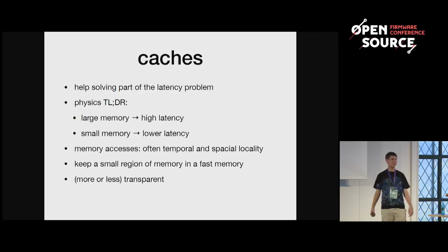What's used on some ARM microcontrollers is the tightly coupled memory. That's an SRAM that sits rather near to the processor core. But that's only mapped in a certain location and doesn't accelerate the rest of the memory, and you have to explicitly use that memory location, so you have to adapt the software. For some special cases it makes sense, but for the general case it's not that feasible.